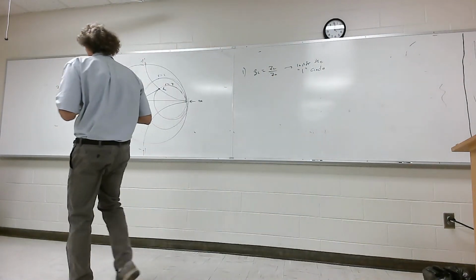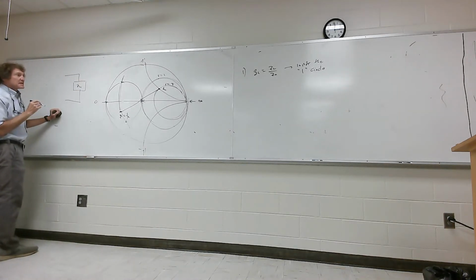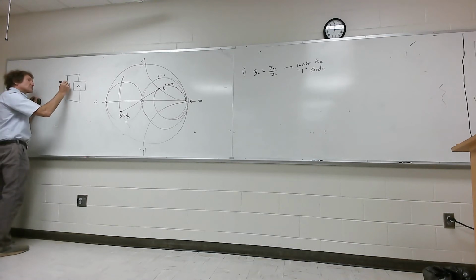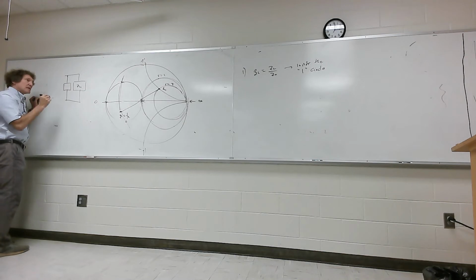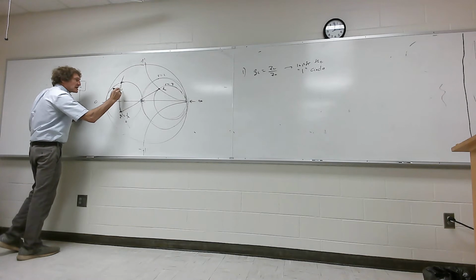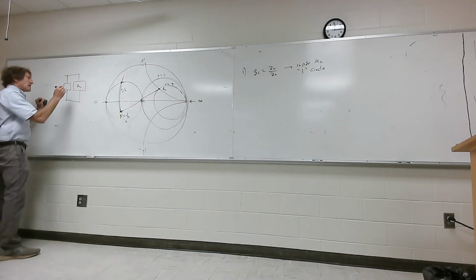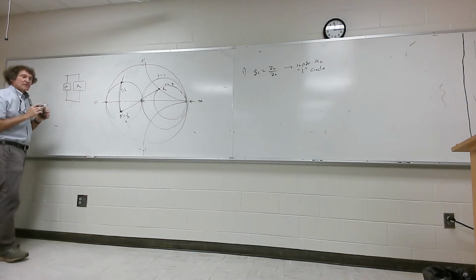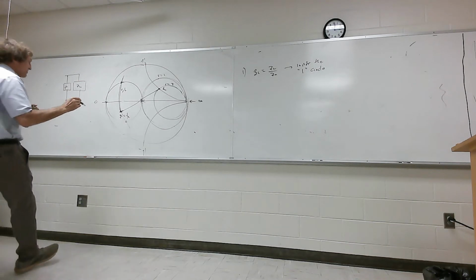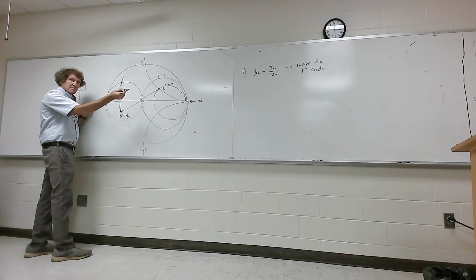So, for this one, I'm assuming that the normalized impedance is in the one circle. Anything I add in series won't help. I have to add in parallel. So I'm going to add a parallel element of admittance. It's going to have a value. I'm going to say it's positive. I'm going to add plus jB here to go from this point to the rim. Y'all follow me? So now I have jB that I'm going to add there. It's an admittance. Now I'm on the rim, right here. And I know if I'm on the rim and I take 1 over that, I'm back to the impedance domain.